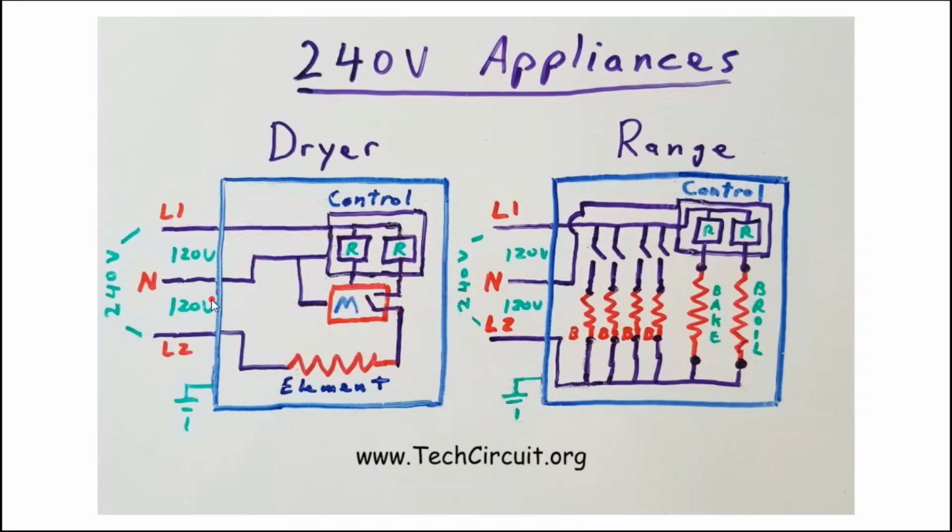So this dryer would run, but it would have no heat. Suppose you went out on this service call and you decided to use neutral as a reference point to test for no heat. And this is why it's not really a good idea to do that. What you would do is measure from neutral to L1. If you measured from neutral to L1, you would get 120 volts as expected because you do have 120 volts there.